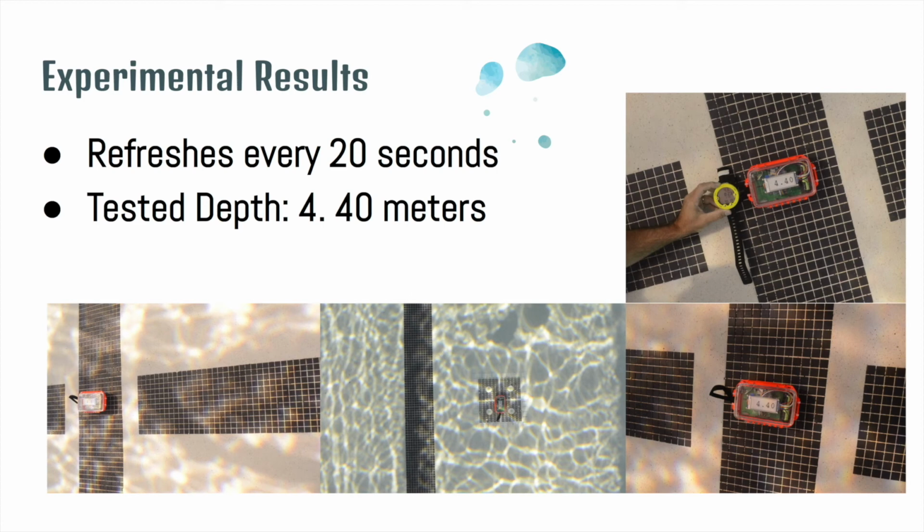We tested DC by placing the device at 4.40 meters underwater and compared the values to a diving watch in order to test for accuracy, as shown. The diving watches have a reported accuracy of 0.1 meters. When DC displayed 4.40 meters, the watches displayed 4.3 meters, but the watches do not go to the hundredths place, so we do not know if the watches truncate the depth values.